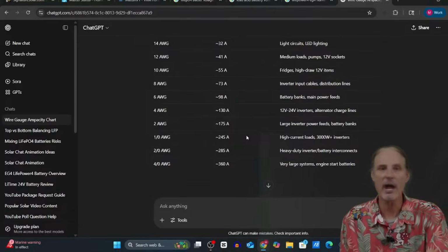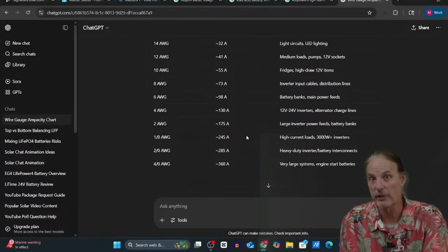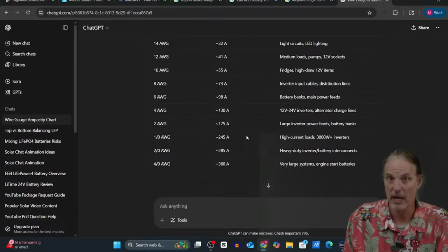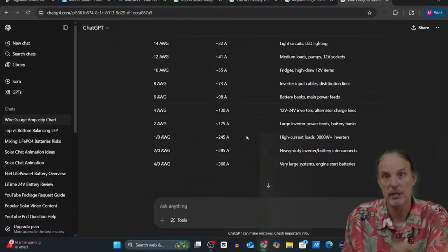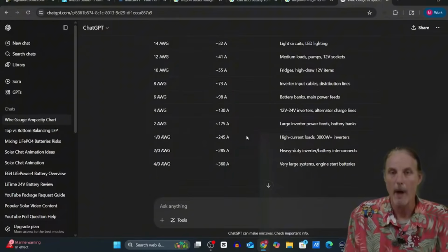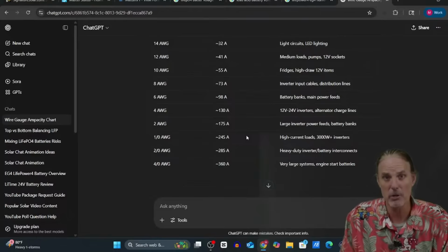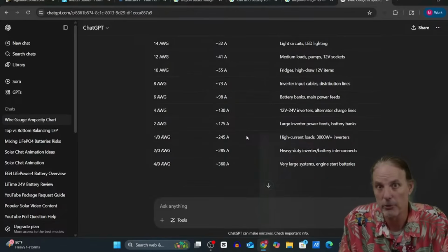Now, if the wire can support 200 amps and your BMS is only 100 amps and you want to protect the BMS from it, then you could put in a smaller fuse and protect the BMS. That would also protect the wire. But make sure that you don't have components that are going to burn and melt down if you don't put the right fuse in there.